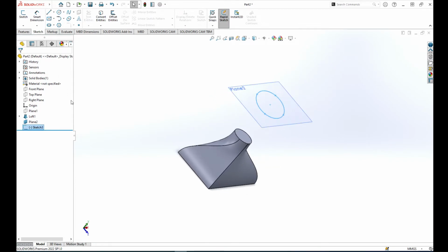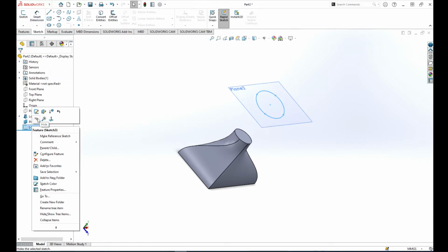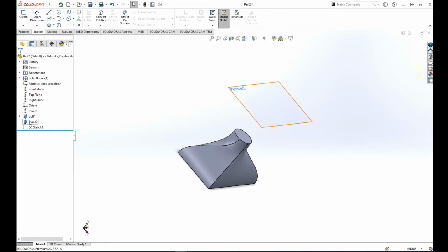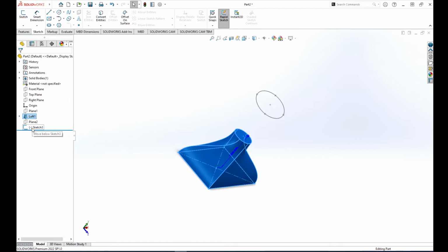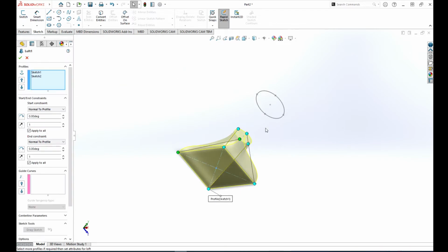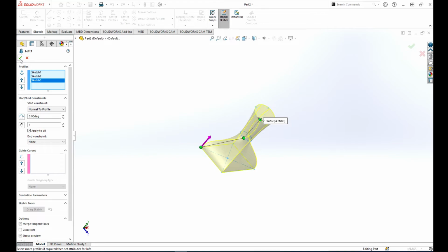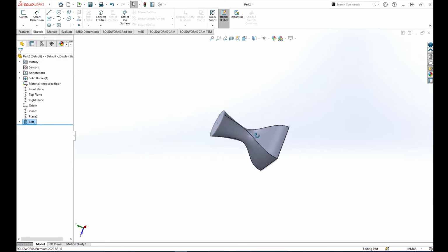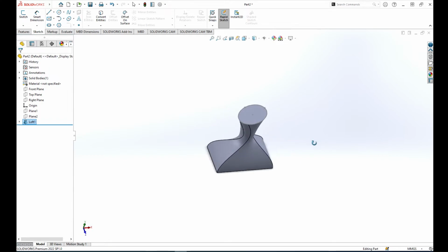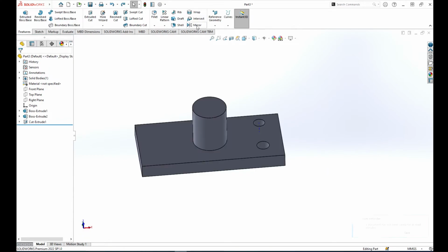So we can have any shape, be it rectangle, be it circle, be it ellipse, any shape in there. So here you must pull the loft feature below the sketch, so that when we edit the sketch, you can see the sketch. The order in the design tree is very important, because if you want now to edit the loft, it has to happen after the sketch. So now you can see how that one came out.